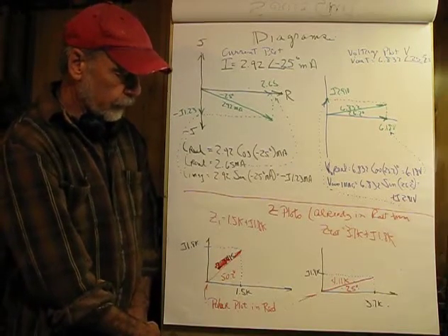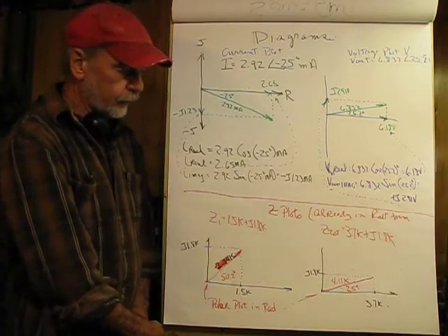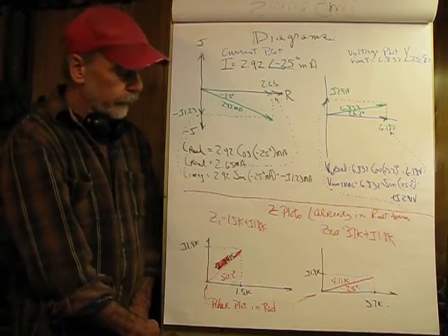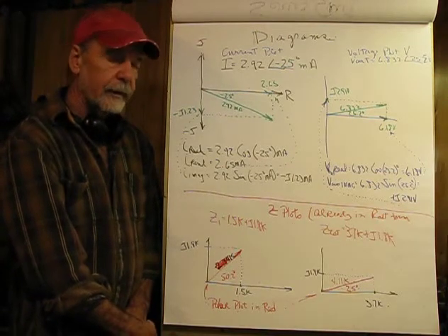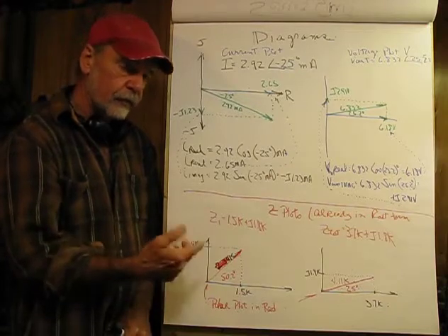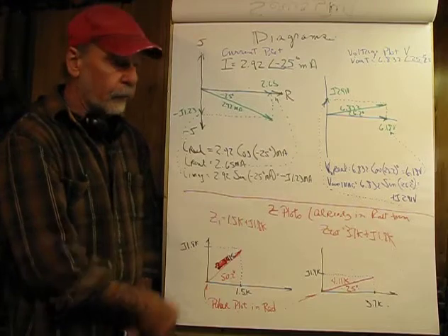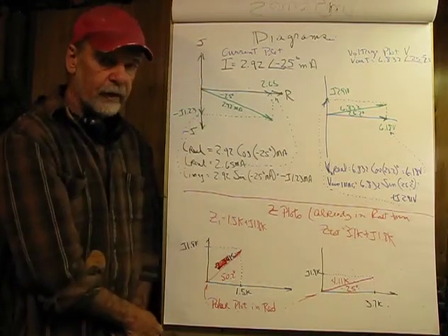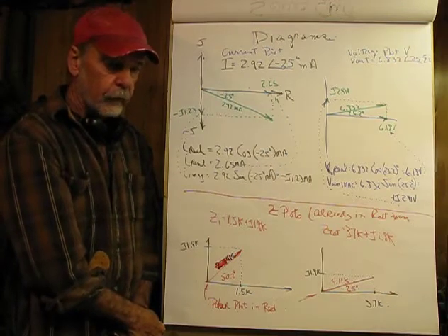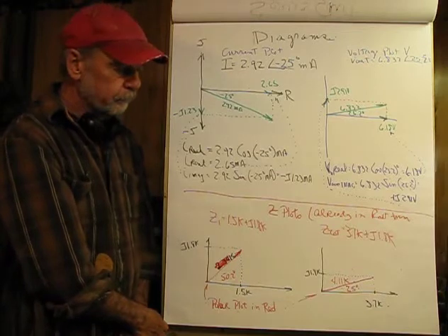So that's basically the form for finding any series circuit. Does not matter if it has an L or a C, how many R's. In a series circuit, what you need to know is that the I, the current, is the constant component. If you have an L and a C, remember they're opposites, so you're going to end up subtracting one J value from the other, and the largest absolute value will determine the flavor of the circuit.